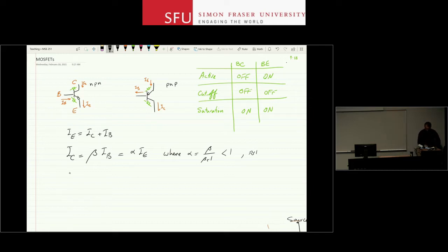And then the other relationship we had was between the collector current and the base emitter voltage, which was similar to a diode relationship. We see that, when we had the discussion about the physics of this device briefly, we mentioned that when you turn on the base emitter diode, you inject a lot of carriers from emitter into the base region. So that's your forward bias diode. The reverse bias diode of base collector, if you make it really close to that first diode, the base emitter diode, will gather all of those carriers and put them in the collector region.